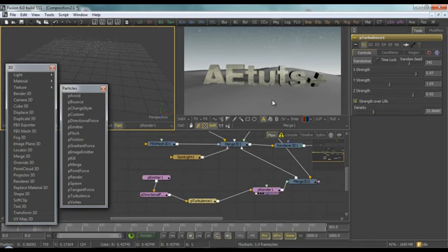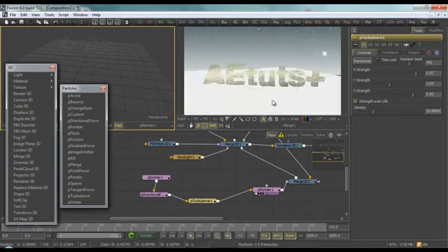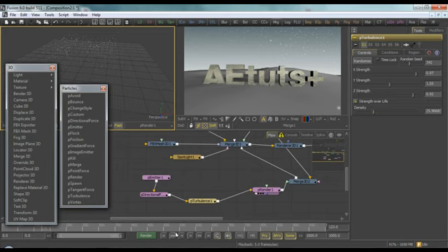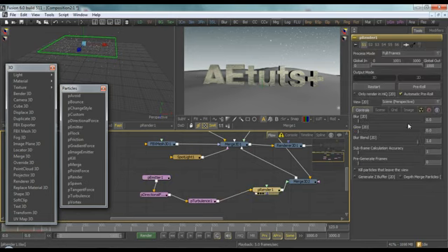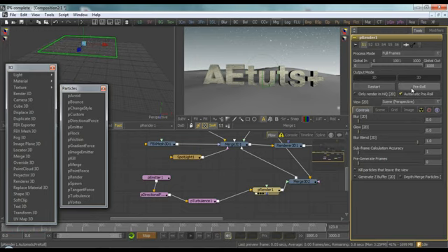And we are not yet satisfied with the particles. So stop. Go to emitter. No, go to particle renderer, and we have automatic pre-roll. Just push pre-roll once again, and select pre-generate frames.